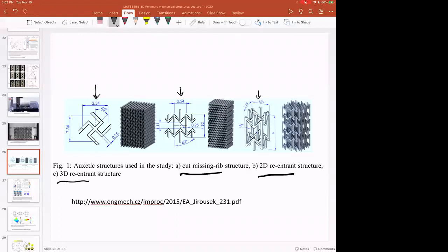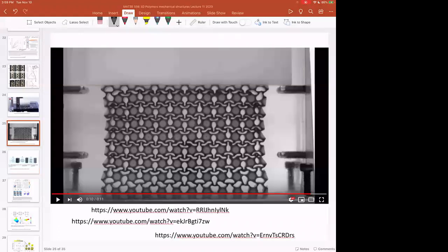And then in terms of printing technology, these types of structures are generally accessible with stereolithography, especially at small scale. But you can imagine that this could be made by SLS or even FDM, depending on the length scale that you wanted to use. And of course, we can do elastomers, or TPU elastomers in SLS, or TPU elastomers in material extrusion AM. While a lot of the examples have to do with stereolithography, we'll see some other examples where different printing technologies are used.